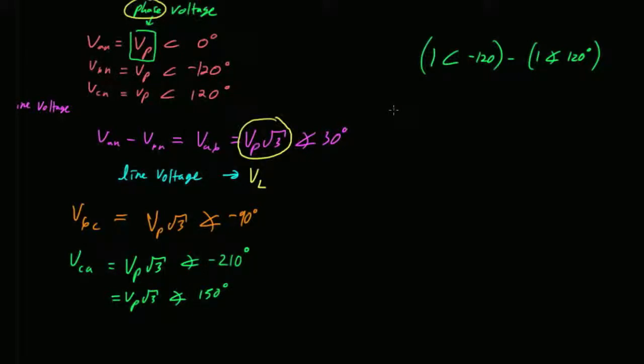How do you always subtract complex numbers? Can't do it in polar. Got to do it rectangular. So convert them both to rectangular. Add the real parts. Add the imaginary parts. Then convert it back to polar, and that would give you root 3 angle minus 90. What's that? That's awesome. Then just do it in polar. Right. I mean, that's desirable.